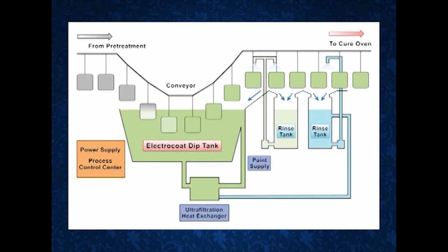Paint layers in case of automobiles. Now, the most common types of paint examined in the crime laboratory are finishes from automobiles. Most cars have 4 coats. Some luxury cars have more than one top layer coat. The organic coatings used in case of automobiles comprise electrocoat primer, primer surfacer, base coat and a clear coat. Let us discuss in brief about them.